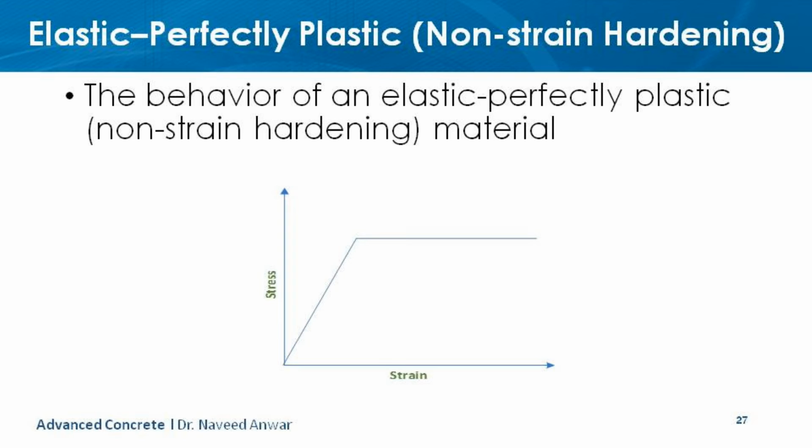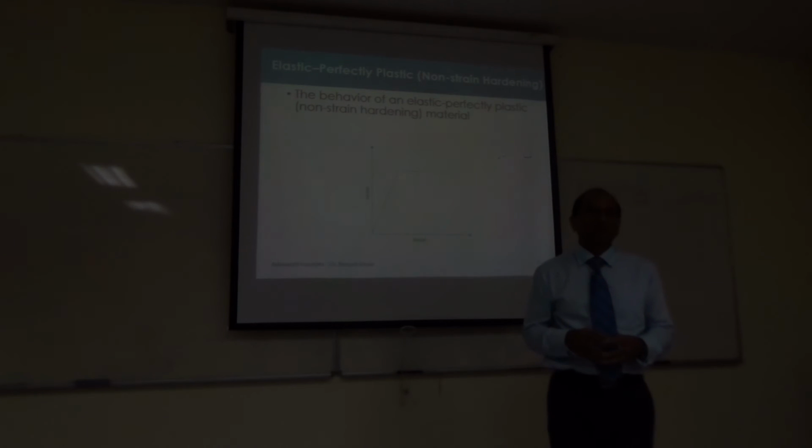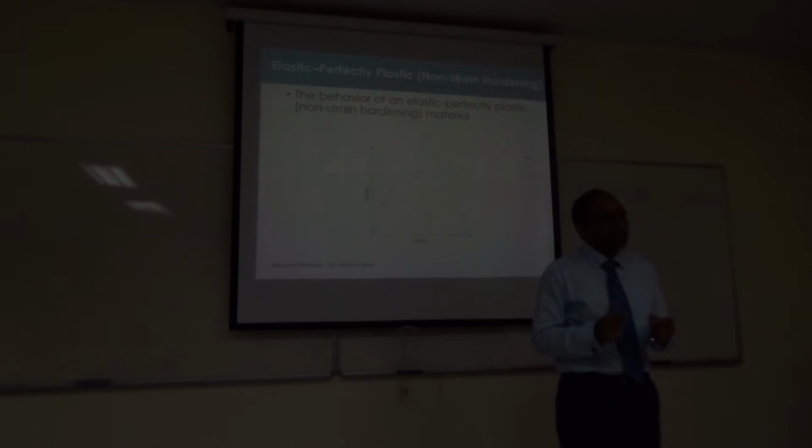Normally, this is how we represent many materials. Most of the real materials can be simplified into this shape. Linear, perfectly plastic, bilinear materials, represented by 2 lines. So one portion for the linear range and one portion for the non-linear range. Just make it like that, simplified. And this is very good, because it makes the calculations very easy. So a lot of materials, even though they are not like this, can be simplified to be bilinear.